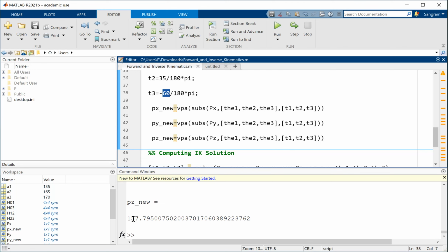So I should have the G code that is generated from this CAD geometry. That is exactly how the G code works. You have a CAD model and a machining setup, and based on the geometry you solve the inverse kinematics problem and convert that into, I don't know if you have seen the G code. You program that inside the G code and the machine then runs the G code.